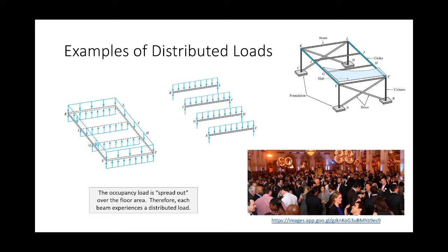And yes, sir? Are there like set loads for things, or do you have to figure that out? That's a great question. So the question was, are there established loads, or do you have to figure that out? So the short answer is yes, there are established loads. We talk about that a little bit more in some of the design courses, like steel design or concrete design, when we really start getting into the details. One of the most common guides that we reference in engineering is a guide called ASCE 7.